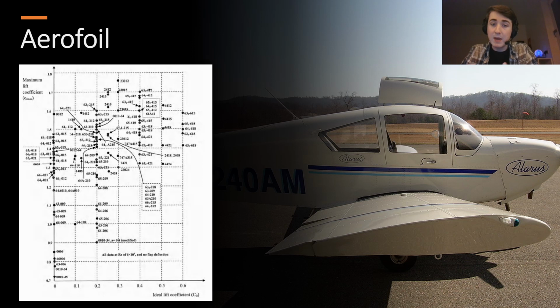Now it's time to select the best aerofoil for our aircraft. I selected a 5-digit series aerofoil due to them having a higher lift coefficient and a low pitching moment compared to other aerofoil series. I decided to go for the NACA 23012 because it had the highest maximum lift coefficient out of all the existing 5-digit aerofoils, even though it only had a maximum lift coefficient of 1.76, which is 0.07 away from our desired value. I was sure this aerofoil was going to meet our specific requirements compared to any other existing aerofoil out there.